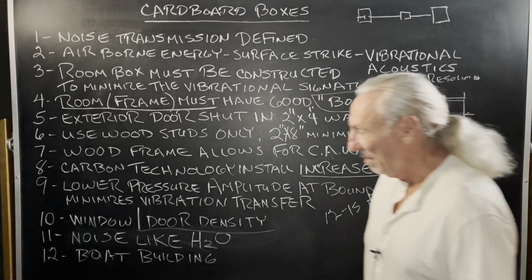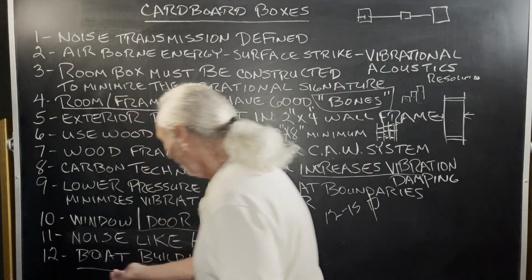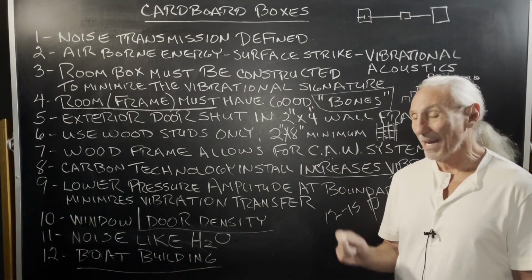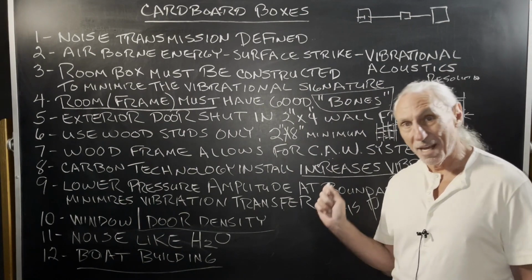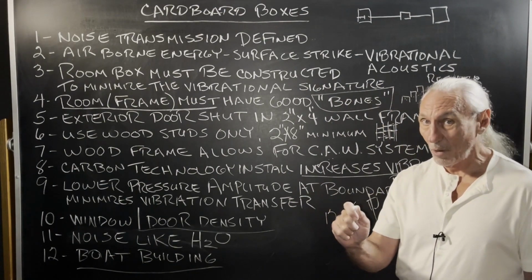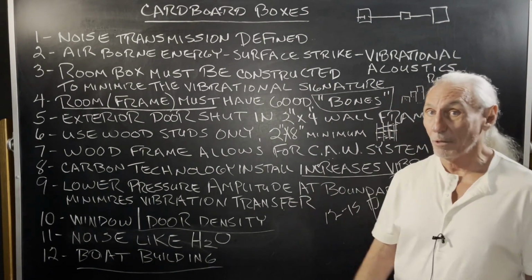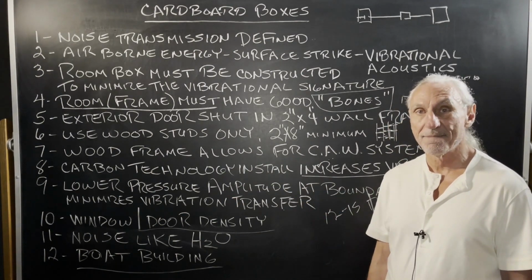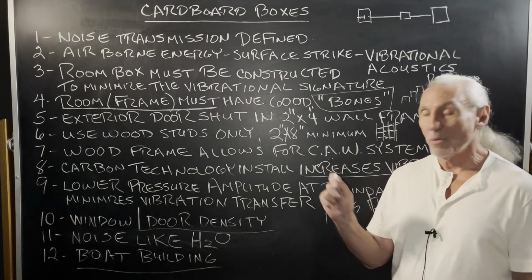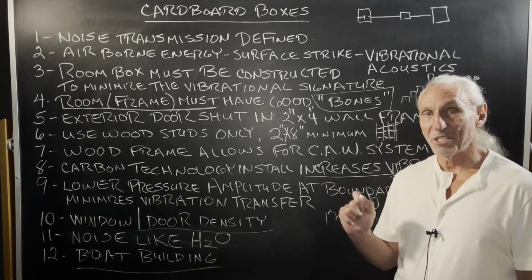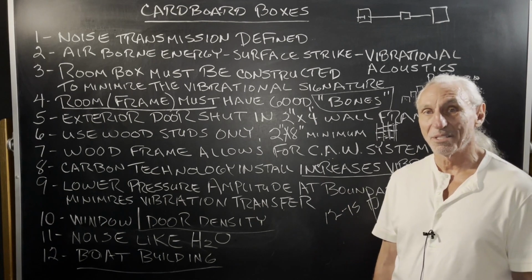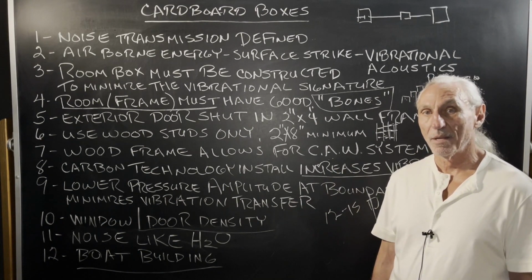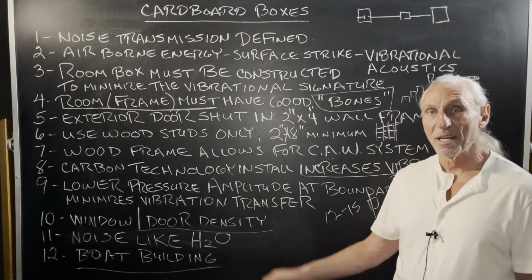So I always tell people when they're designing a room, we're really building a boat. It has to do 2 things. It has to be strong, because it has to handle the force from the waves of water and the waves of low pressure energy, right? Waves and rays. And it can't leak. Can't leak at all. A 1/4 inch hole in a wall that's designed to stop noise is a nightmare. It can defeat the whole performance of the whole wall. So you have to be careful. It has to be strong and it can't leak.